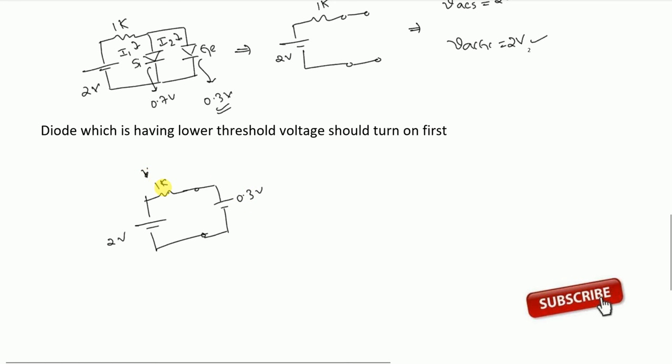Next, find out the VAC across silicon diode again. So what will be VAC here? It is nothing but 0.3 volt because these two are in parallel. So VAC across silicon is 0.3 volt, which is less than V threshold. Why? V threshold of silicon is 0.7 volt. Because VAC across silicon is less than V threshold, it will be in off position. So what is the answer, guys? I1 equal to 0, I2 equal to (2 minus 0.3) by 1 kilo. That is 1.7 milliampere.